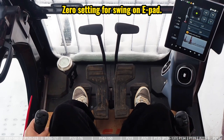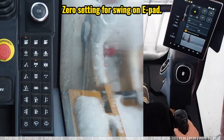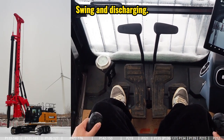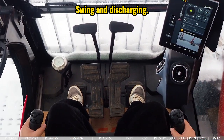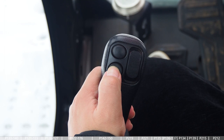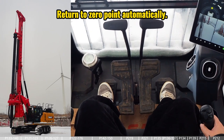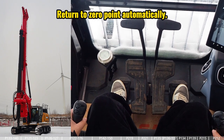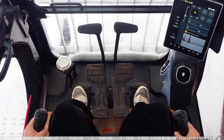Now, first step, we need to set the 0 point for the swing in the E pad. And now unlock the swing. We go to the place for discharging. And after a few seconds, we discharge all of the soil, so we need to go back to continue the drilling. We just double click this button, and then the machine is going to swing back to the original place for the drilling. And when this goes back to the main page, it means the auto swing has been finished.